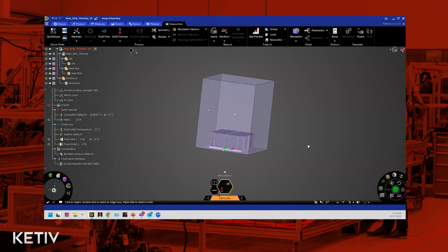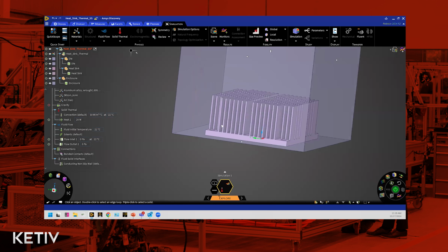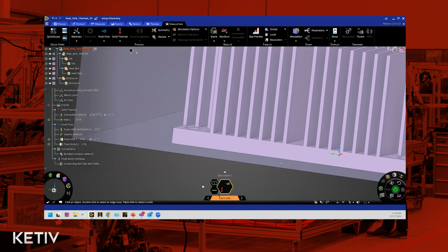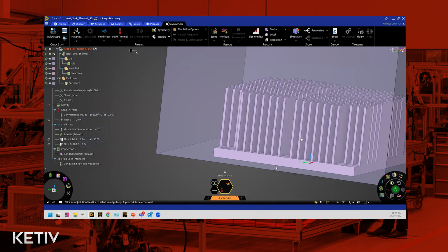The only thing that you have to worry about now is, depending on the geometry that you are simulating, you want to make sure that the fidelity of your Discovery session is high enough to capture the thickness of the fins, right? You want resolution in those thin fin solid sections. So if you look at the fidelity bar over here, it's on the left side, so the fidelity is quite low. So I would recommend dragging it all the way to the right for a problem like this.